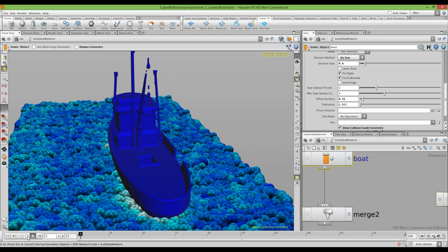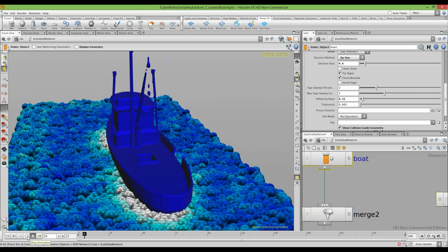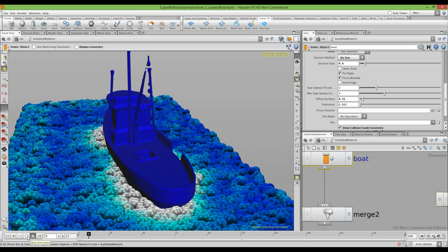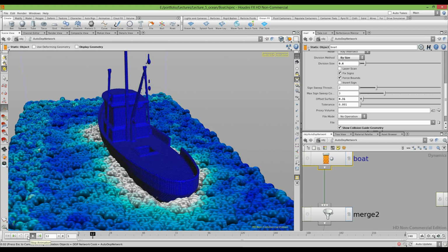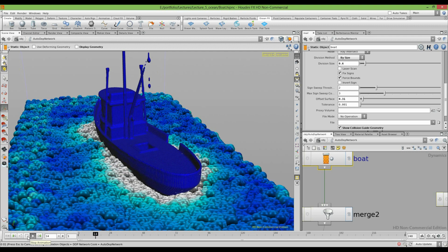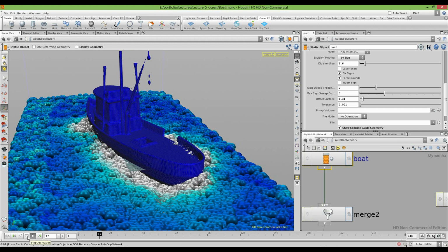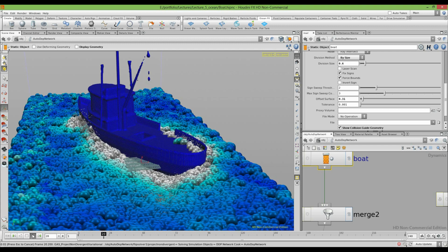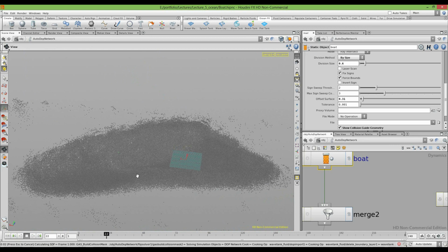My suggestion is that even if increasing the amount of substeps is not helping now, then I need to decrease the resolution of the liquid. But this will be too heavy for calculations, because it's pretty common to wait from 2-3 minutes per frame up to a few hours per frame. Depends on your machine, your resolution of the liquid, and so on. But yeah, it will be long. But okay, you see now that the liquid is colliding way better. It's still coming through, but this looks like the resolution. Okay, and these are particles generated like white water or air bubbles.